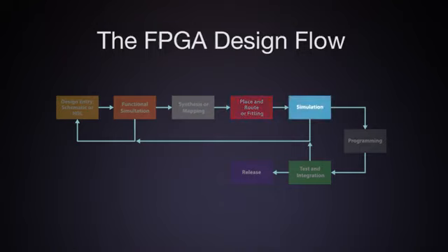Timing analysis using static timing tools is then required to assure there are no setup or hold violations in the design. Running another simulation after fitting is done is a good practice and it can uncover timing issues. If analysis confirms proper operation of the circuit, the next step is to use the tool to create a programming file, which is then downloaded into the FPGA device for testing.